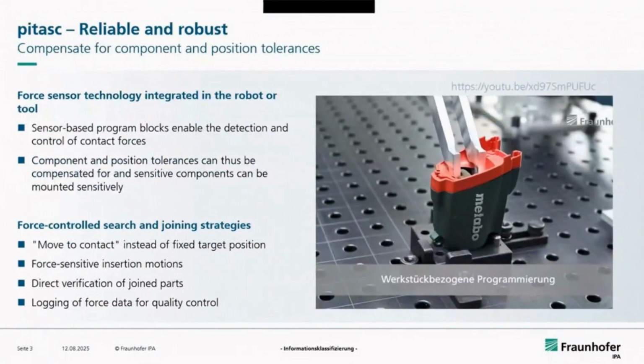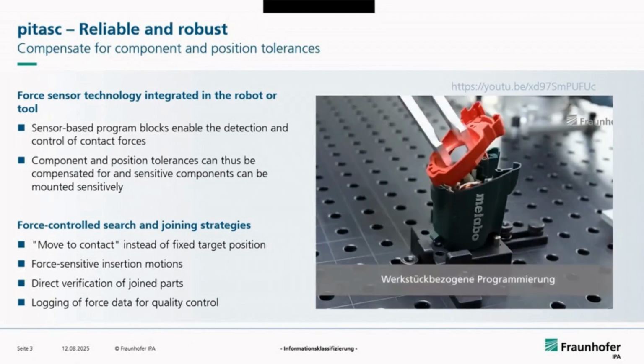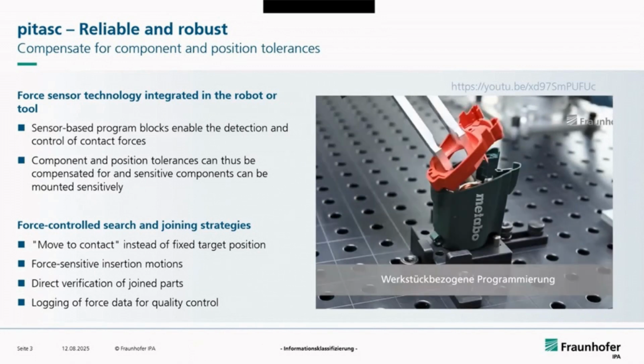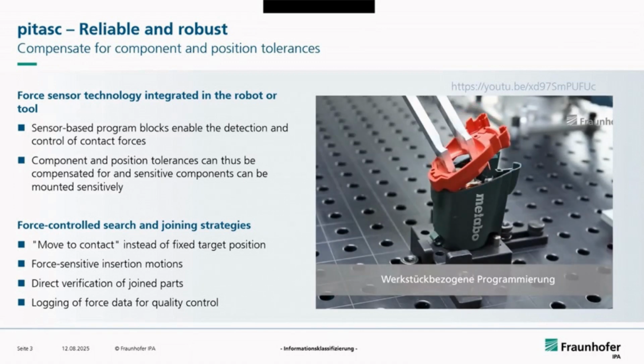One major component is force control and its combination with position-based programs. This approach offers us several advantages. One is the possibility to move adaptively based on the workpiece and feel differences in tolerances. With forces, we can directly verify if joint parts are connected or if the joining process was successful or not.